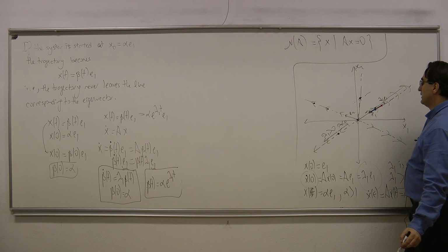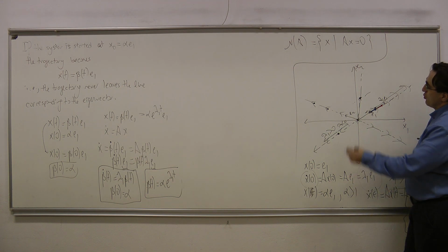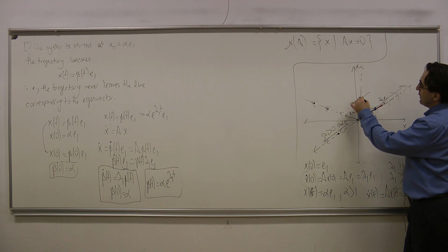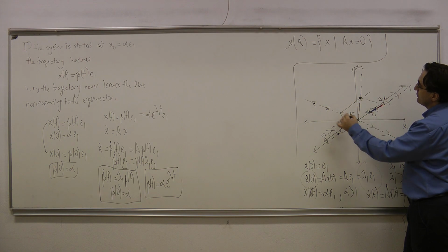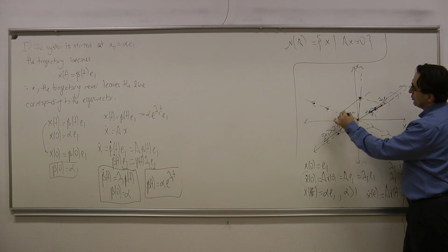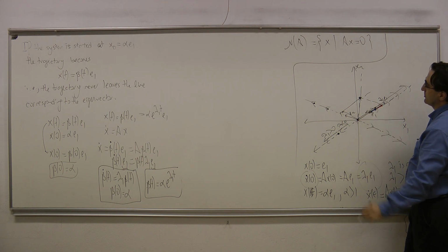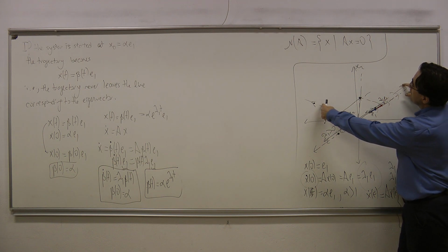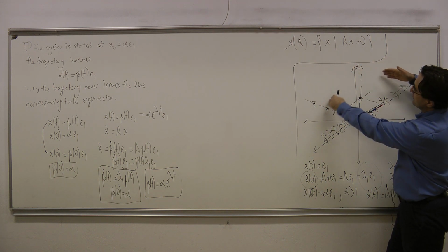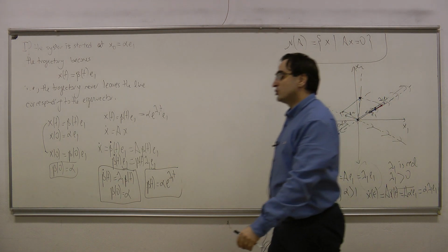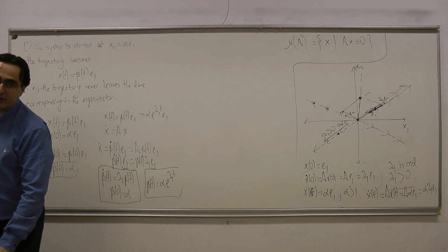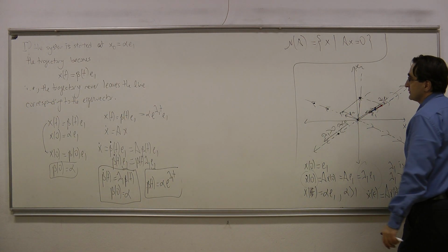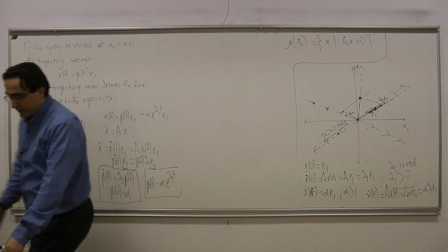Okay. And actually what we're going to do when the state is not on any of these lines is try to decompose the state into two parts. The first part is going to be on this line, and the second part is going to be on this line. Then we're going to propagate these components, and then combine them once more. All right? So this is going to be made by a state variable change in the original linear system. So the first thing that we consider is case 1.